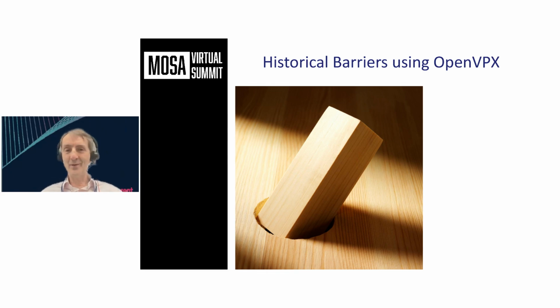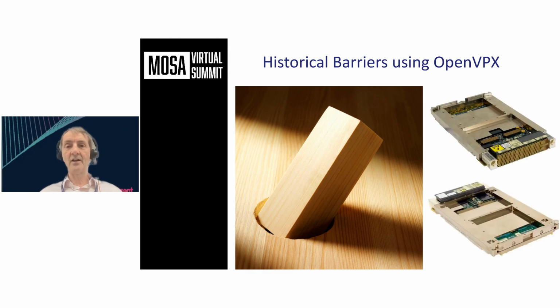However, Open VPX particularly offered tremendous flexibility, a well thought out standard, lots of work went into it, but having vendor defined user IO and the flexibility to implement a fabric of choice on the data plane meant that pretty much every single system was unique. And in many cases that required individual backplanes, it required individual connectivity. And what that really meant is that if I look at the sort of products that Concurrent had in the marketplace, for every generation of processor board, we probably defined a different set of user I/O. So we sort of shot ourselves in the foot because customers who are using generation A boards couldn't just remove a generation A board and plug in a generation B board because the backplane I/O was incompatible.